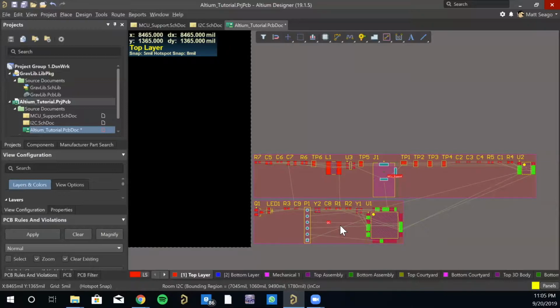Do you have any actual mechanical constraints to your size? Do you have mounting holes? Do you not? If so, what size? A good mounting hole size I've found is M2.5, but maybe you have something different. There's a lot of variables that go into layout. And I personally like to keep things as compact as possible, but maybe for your specific board, you're allowed to have a ton of real estate on it so you can spread things out.